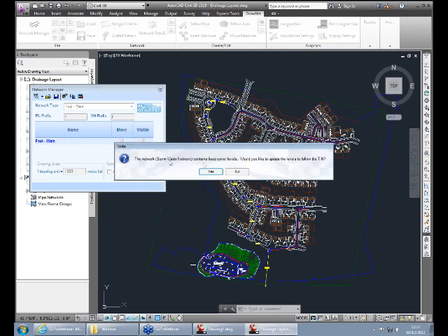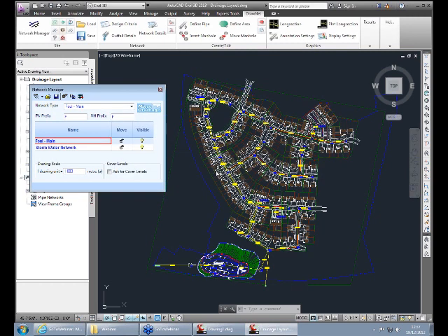On that first warning, I'm asked if I would like to update the cover levels for the design with the TIN levels built into the AutoCAD, or in this case Civil 3D, model. I'll go yes on that, and that will automatically update all my cover levels. You'll now see the network following the main road layout across the site. We've now got both networks in the list in our network manager, so I'll make sure the storm water network is populated.